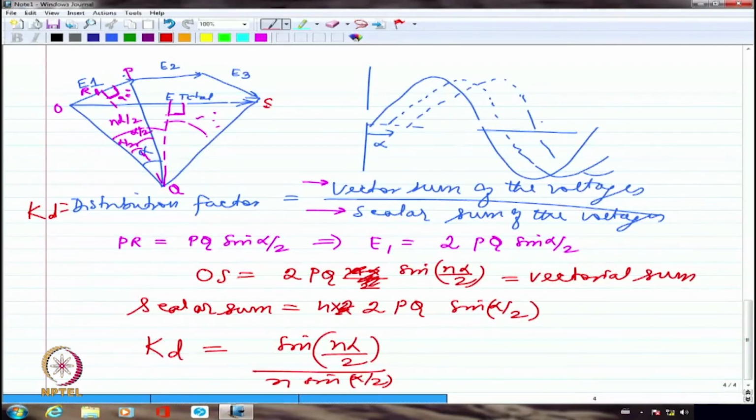So I should say this flux, what we actually originally wrote as 4.44 F phi into number of turns, this corresponds to flux per pole. Because there are a number of poles, I can have that multiplied by so many poles. Because for each of the poles, there will be one A sitting: A, A1, A2 and so on if I have more and more poles.